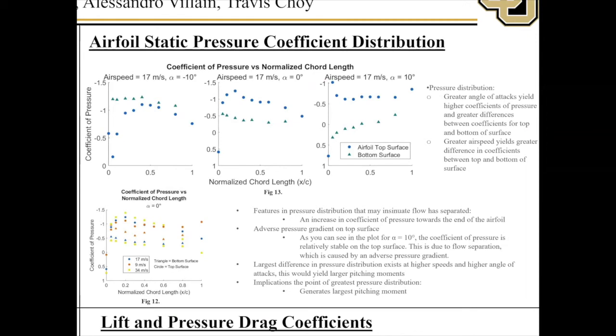However, what we also found was as velocity decreases, or as the pitch increases, we see a higher pressure occur at the trailing edge, indicating a separation of the boundary layer. This is due to the adverse pressure gradients occurring at this location, which cause a negative flow velocity over the trailing edge, thus increasing the magnitude of velocity over the pressure port, but still separating the boundary layer.